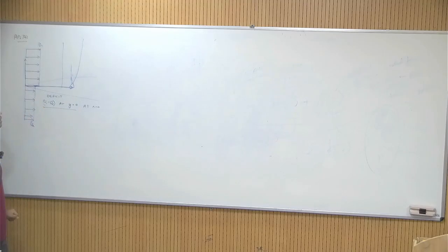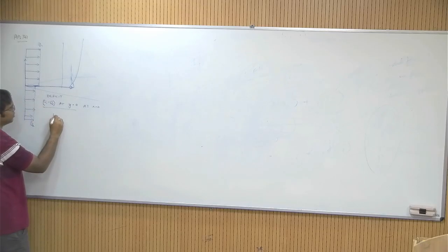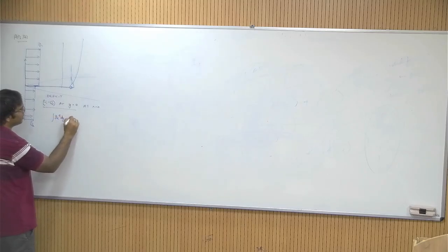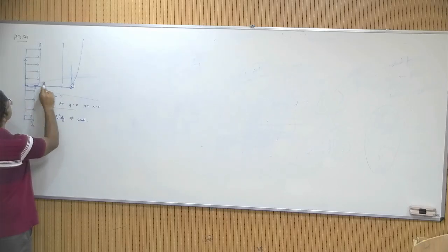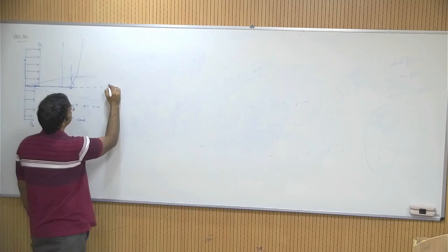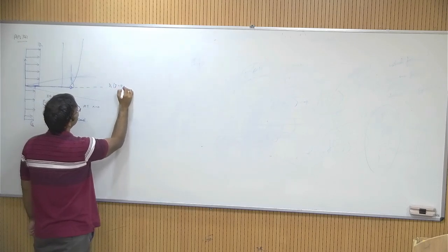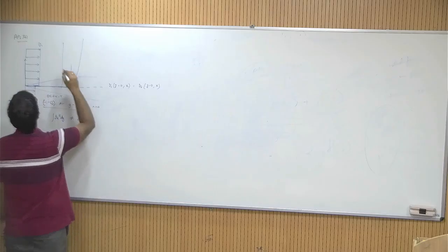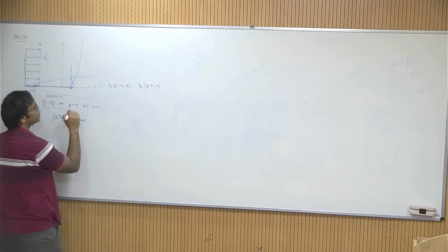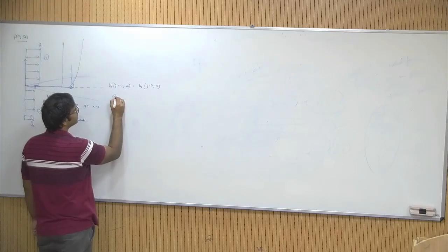and you can look at the boundary conditions that we have used. You can confirm that the momentum integral is not constant in these. Momentum integral will not be constant, so the integral of rho u square dy is not constant here, and you will have to use the boundary layer boundary conditions, the Blasius boundary conditions. So you know the velocity at y tends to infinity, and at this interface you will have to use that u1 for y equal to 0 for all x is equal to u2 for y equal to 0 for all x, where this region is 1, this region is 2,